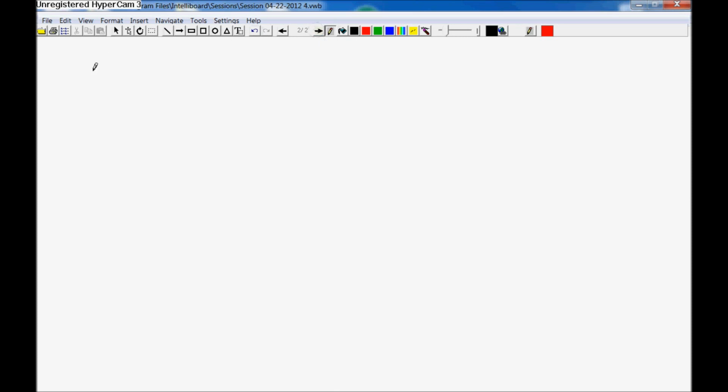So the first one is NOT, and that usually looks like this. So let me redraw that. That's a NOT. It's something with a bar over it, and the logic schematic looks like this. So this triangle defines a buffer. That's a buffer, meaning value in is value out. This dot at the end is what inverts it. So you'll see that in some of the other logic symbols we go into.